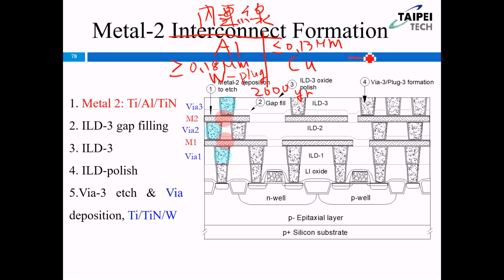And then when it moves on to 7 nanometer, although the main metal material is still copper, right now we introduce cobalt. Someone may say, we don't use the tungsten plug here. Instead, we use the cobalt layer for the local interconnect. And also, someone may say, we don't use the Ta and TaN for the diffusion barrier. Instead, we use the cobalt to become the diffusion barrier for the copper.